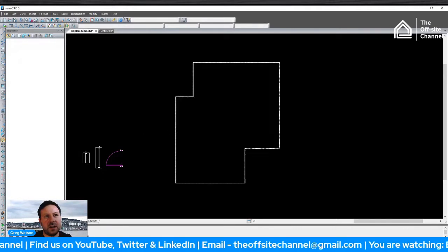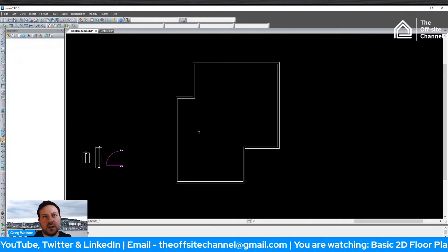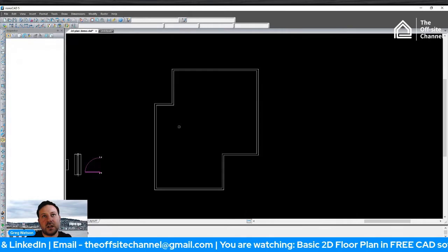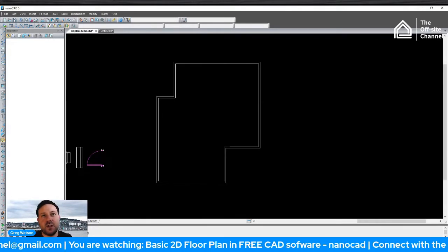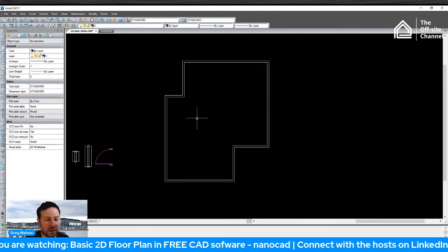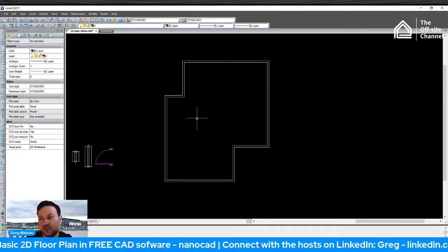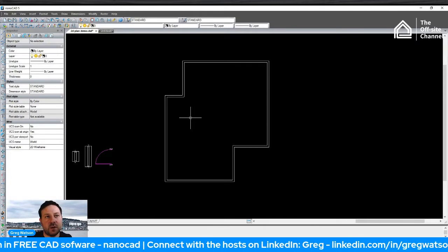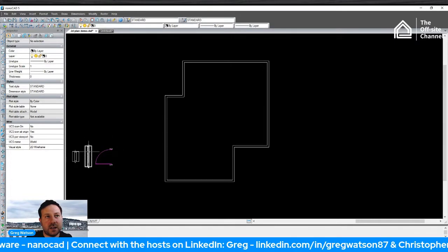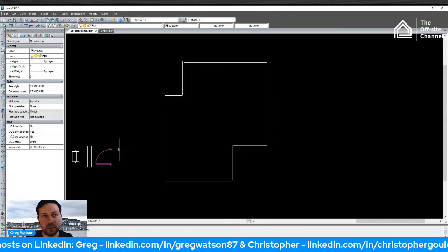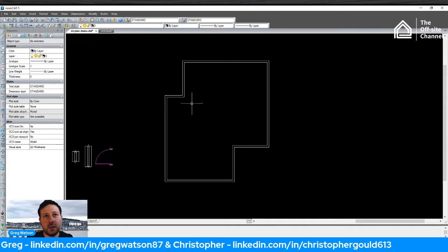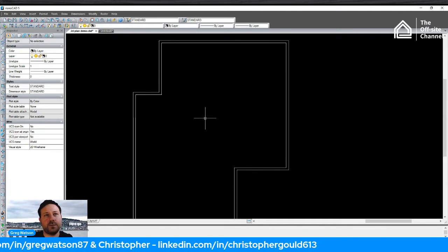We're 95 and internal. So that'll be our external frame, 95 mil, 4 inches. The reason I'm going to do that, we'd normally use 6-inch or 140 or 145 millimeters, but it will go with the external joinery here a little bit better. Just try to keep it as quick as possible on this. So there is our external wall.